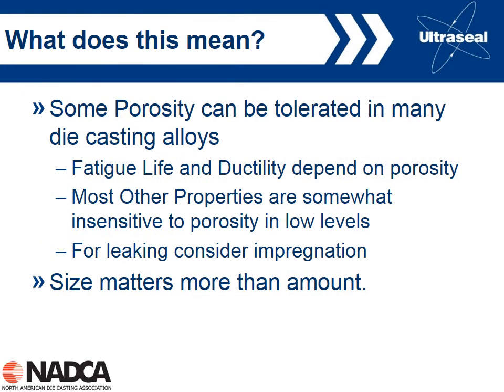So what does this mean? Some properties are very dependent upon the porosity level. Certainly the elongation, ductility, fatigue. Certainly we cannot tolerate a lot of porosity if these properties are important to us. But often porosity is not that important.